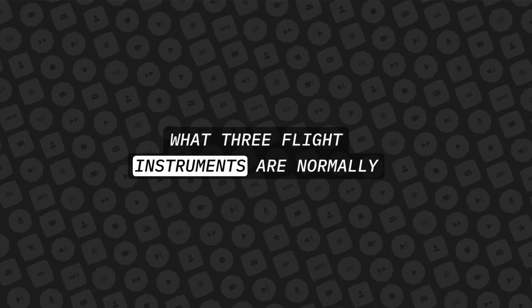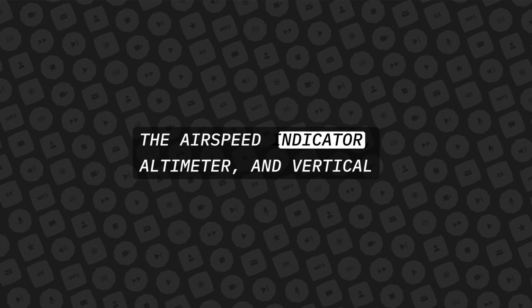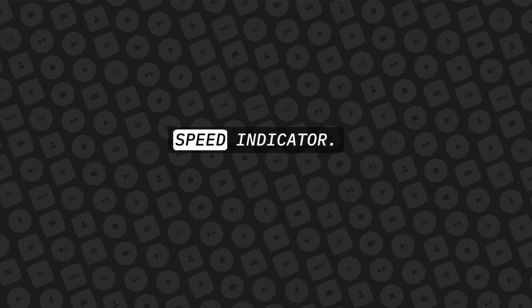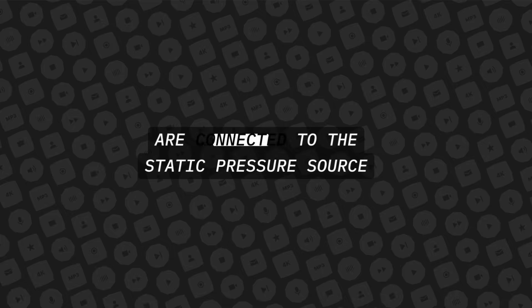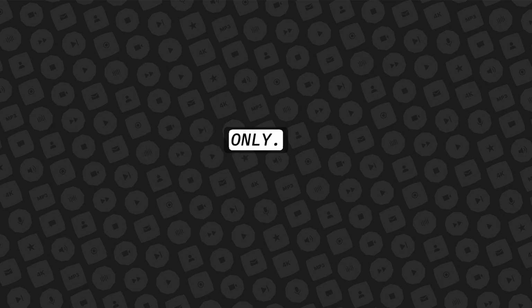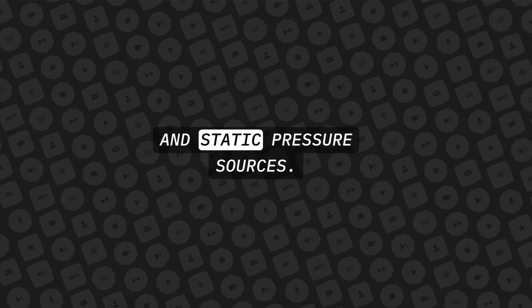What 3 flight instruments are normally operated from the pitot-static system? The airspeed indicator, altimeter, and vertical speed indicator. The altimeter and vertical speed indicator are connected to the static pressure source only. The airspeed indicator is connected to the pitot and static pressure sources.